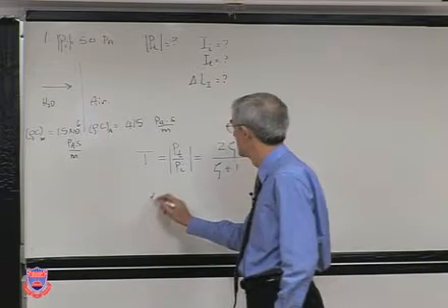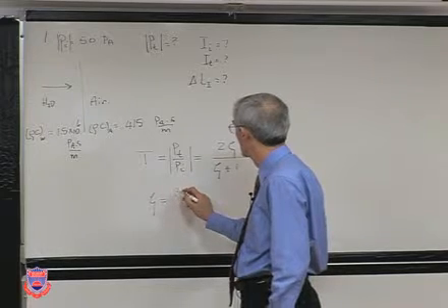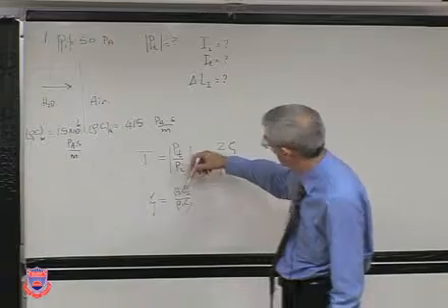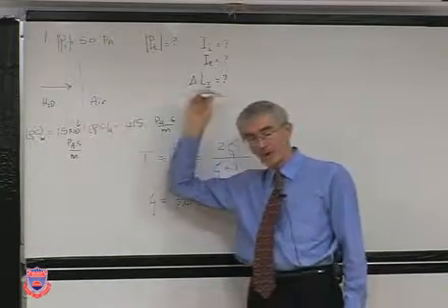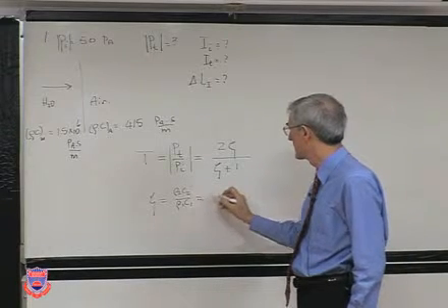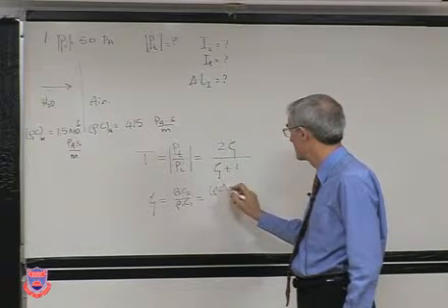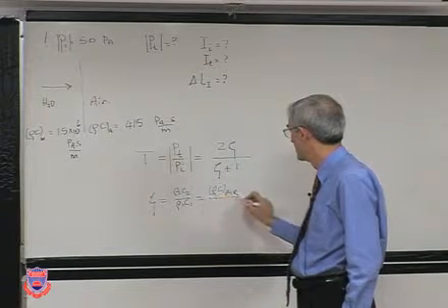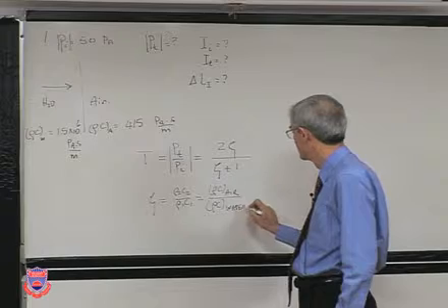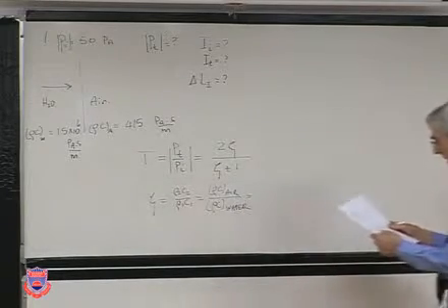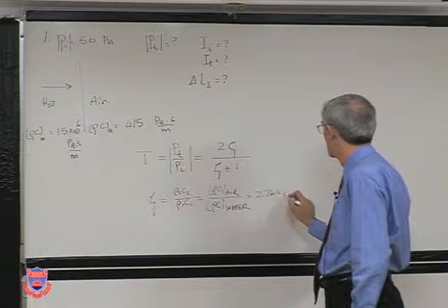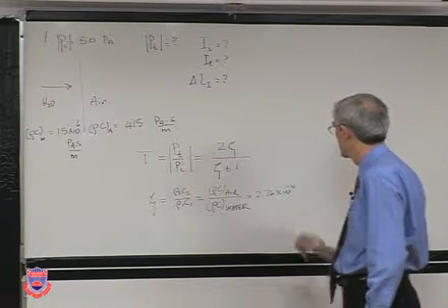And here, rho 2, C2, rho 1, C1, meaning the ratio of the transmitted side to the transmitting side. So that would be rho C air to rho C water. And that ratio is roughly 10 to the minus 4.